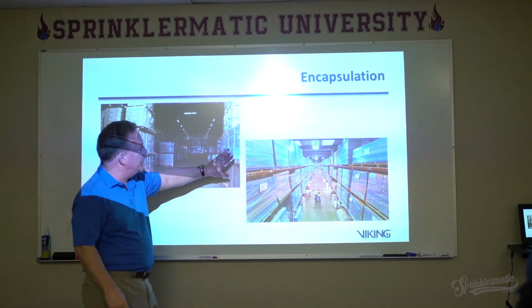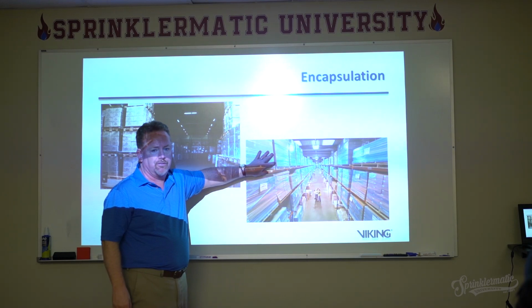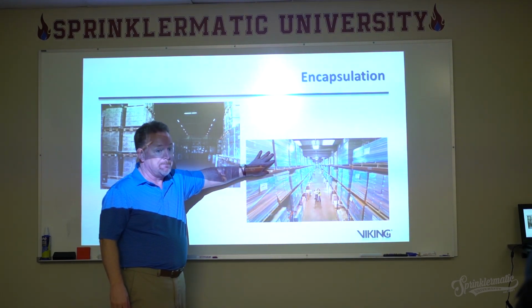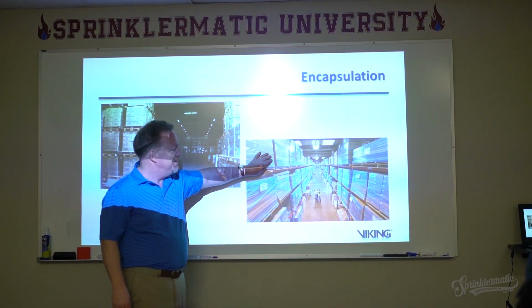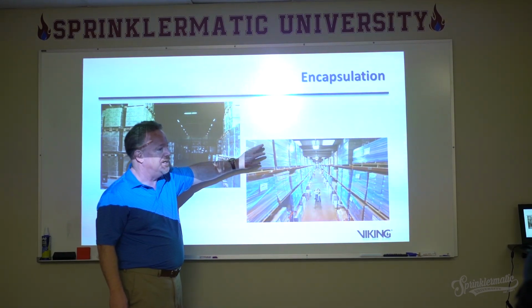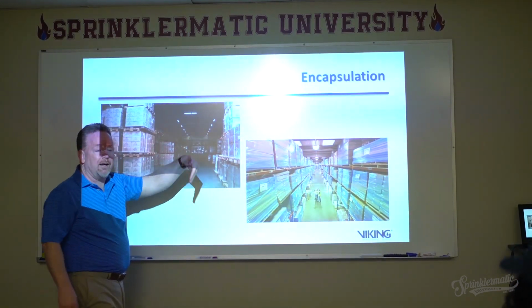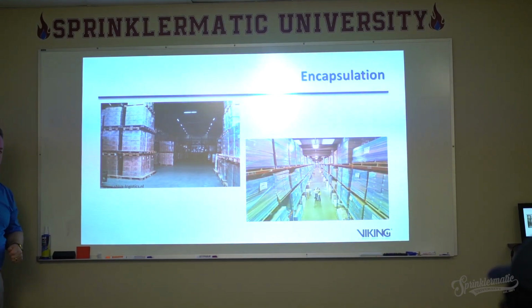Now, why is encapsulation such a challenge or concern for fire sprinkler system design? No water entry. No water penetration, right. The plastic things will burn inside, and the water can't penetrate in. So that's going to have an impact on our design.